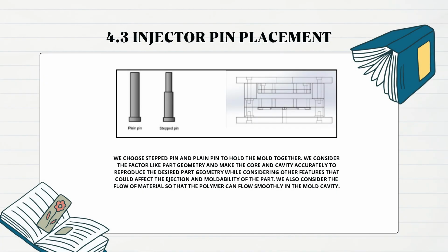Okay, next I will explain about injector pin placement. As you can see in the slide, I have shown you the picture of injector pin placement. We chose tapered pin and plain pin to hold the mold together. We consider factors like part geometry and make the core and cavity accurately to reproduce the desired part geometry while considering other features that could affect the injection and moldability of the part. We also consider the flow of material so that the polymer can flow smoothly in the mold cavity.